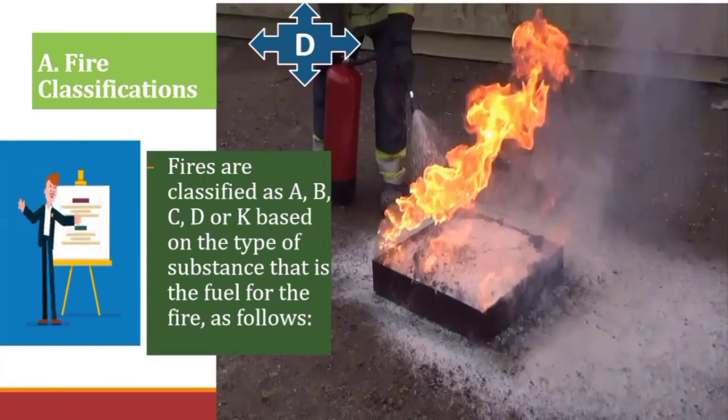So how would you be able to deal with Class D fires? There are dry powder extinguishers intended for Class D fires. The powder inside the extinguisher may vary depending on the type of metal risk it is designed for. Small metal fires can sometimes be smothered with dry sand.